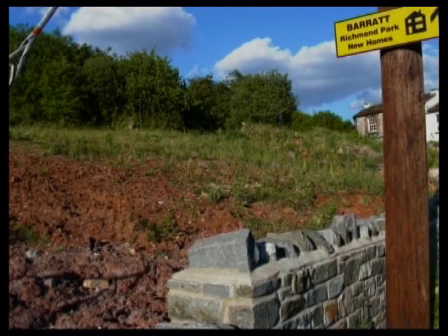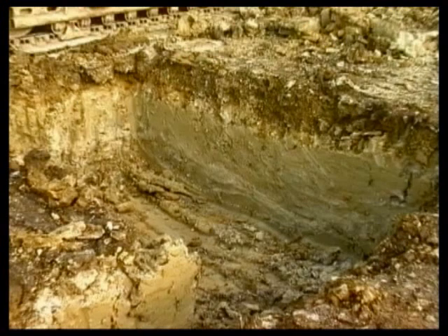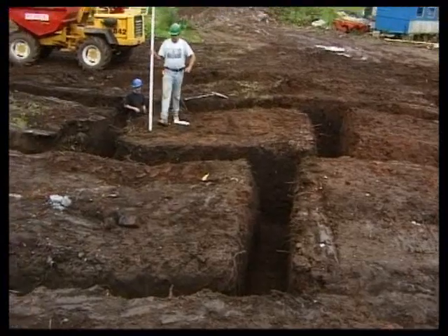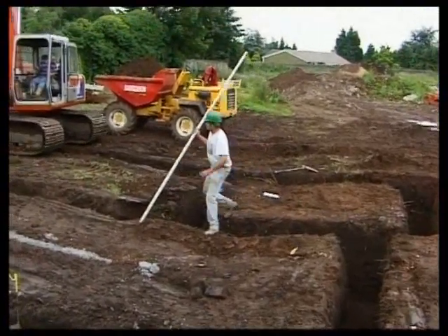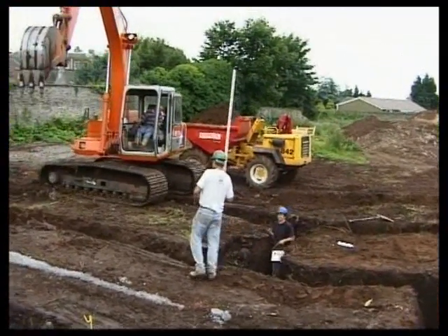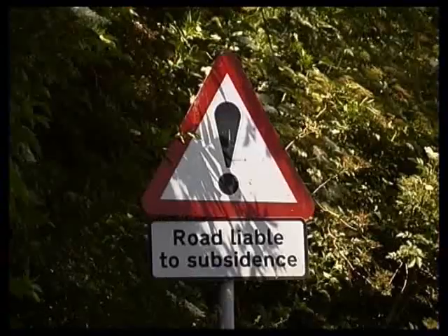Clays have a wide range of bearing capacities and also vary in colour. Their stability and overall strength are affected by their moisture content. Firm clays and stiff clays are ideal for simple strip foundations.